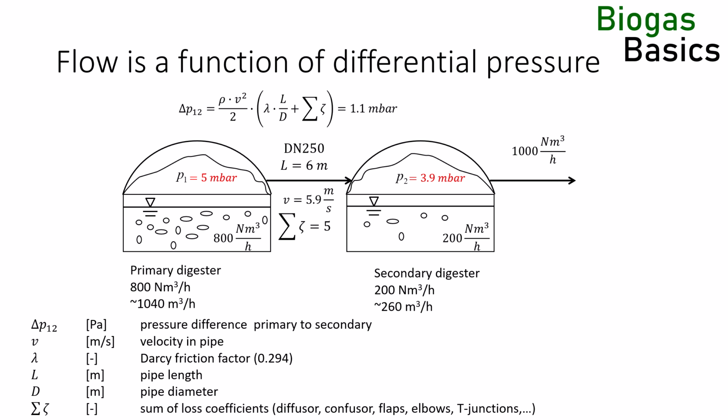The point is, it is impossible to precisely predict all factors affecting the required pressure drop between the two digesters. Therefore, the pressure in the two gas domes cannot be exactly set to correspond with both the inter-digester gas flow and the friction coefficient of the connecting gas pipe.